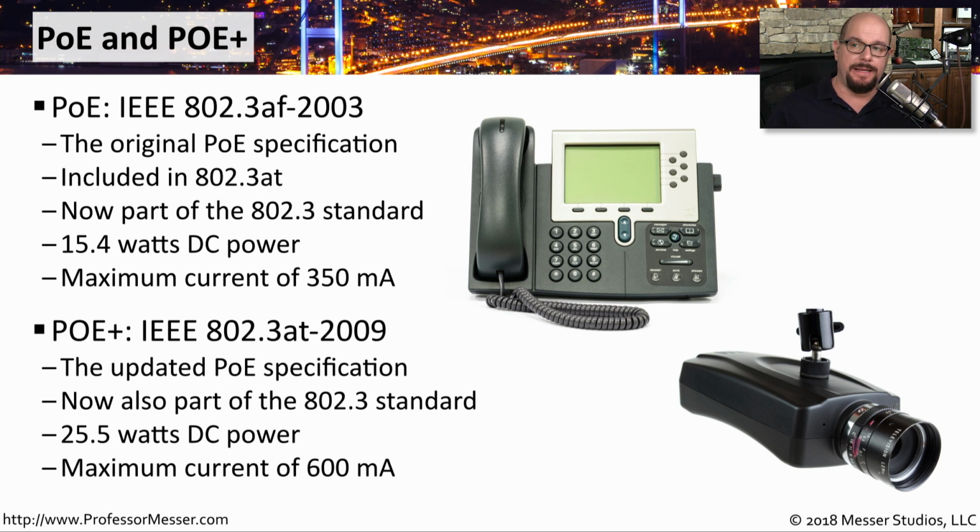PoE was updated in 2009 with the IEEE 802.3at specification, and this specification has also now been folded into the 802.3 Ethernet standard. This increased the amount of power to 25.5 watts of DC power and a maximum current of 600 milliamps.